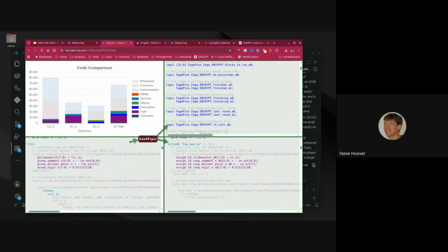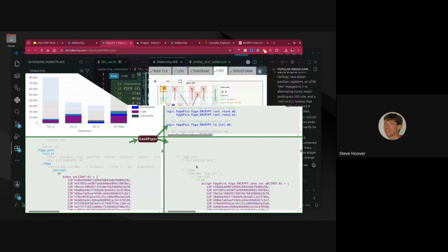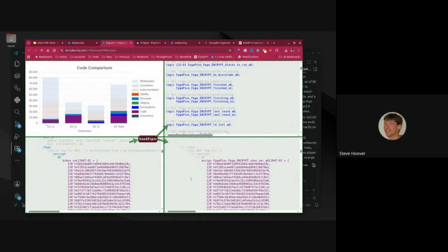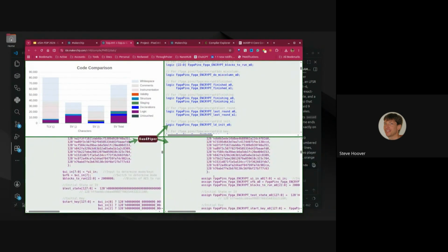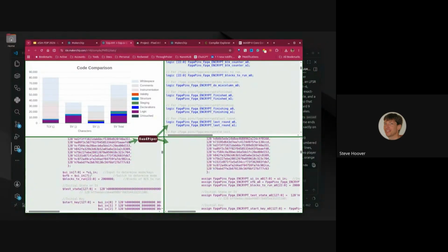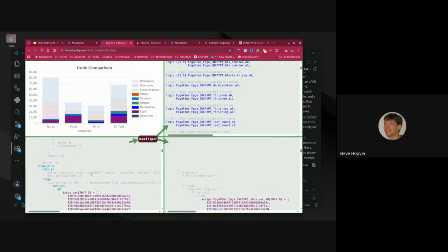The code structure in this translated file is the code structure that you started with. The signal names are long. They're long because they're descriptive. They have the pipeline number, they have the scope. You have that context in TL-Verilog, so the names there are short.